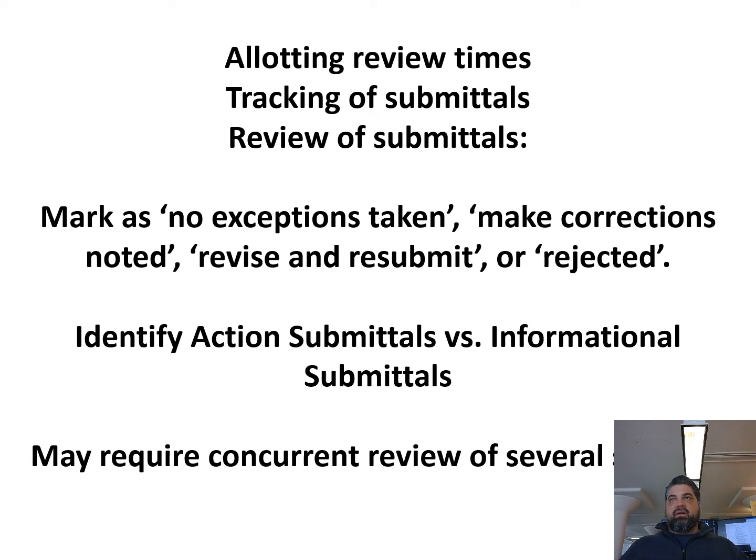And it's really a contractual term, because regardless of what action you take on the submittal, the contractor is still responsible for complying with the contract documents. So as a result, it's really important that you don't say, oh, I approve this, because you could be approving something that is in conflict with the contract documents. So you're just saying, I don't take any exceptions to it.